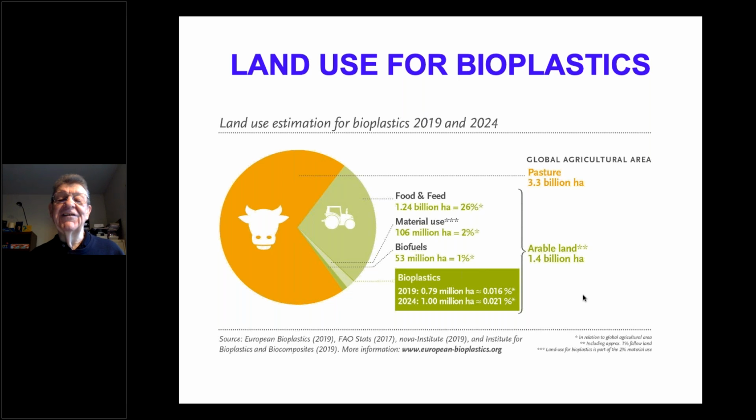So over the last 10 years at least, maybe longer than that, all kinds of compounding technology has been developed to increase the heat distortion temperature. It also suffered from something in the beginning: it went from a ductile to brittle transition when it went into storage. So the impact properties have been vastly improved.